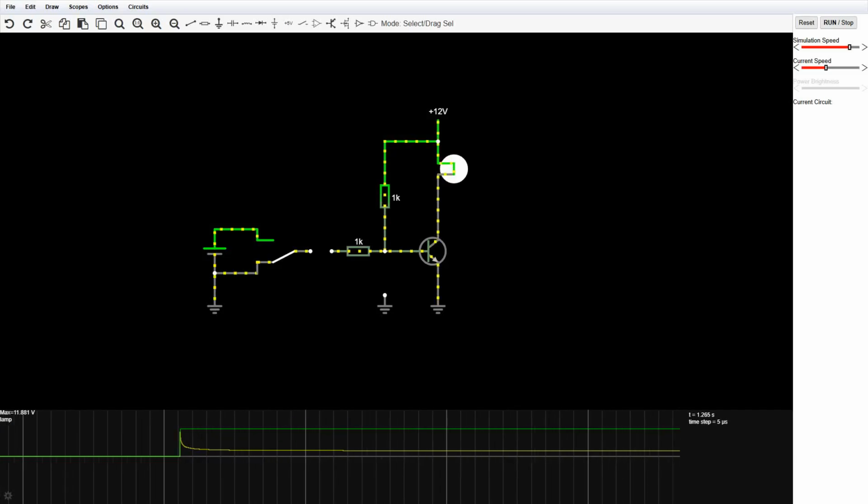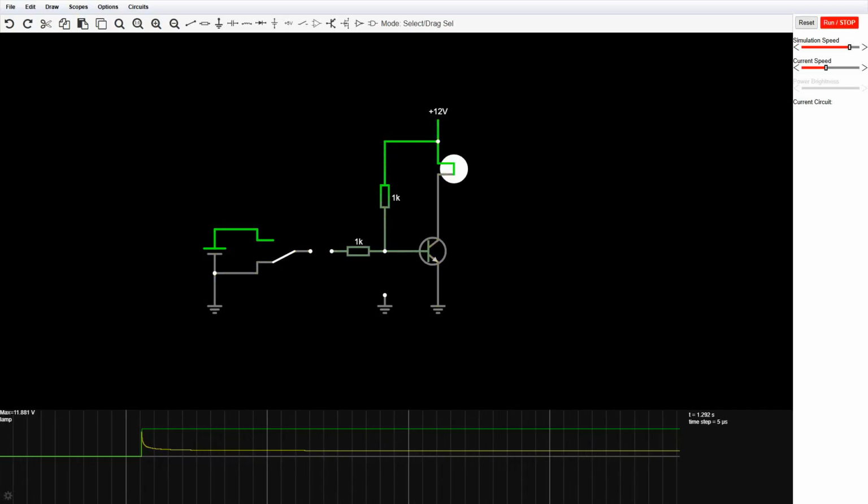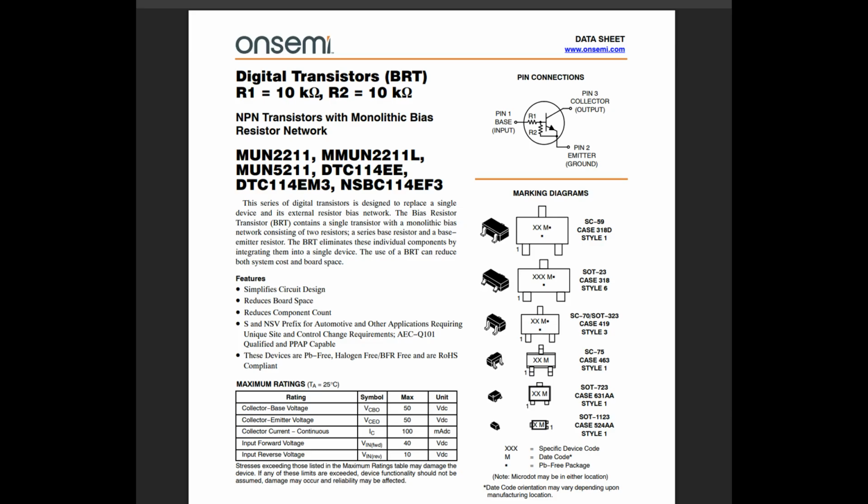Check your MCU datasheet. If you think that we reinvented the wheel, you're right. Our setup is standard. There are even digital transistors with built-in resistors. No extra parts needed. About resistor choice, I used 1K while the digital transistor used 10K.